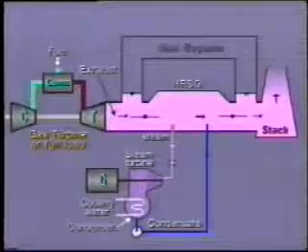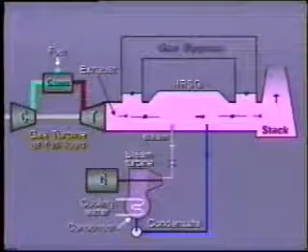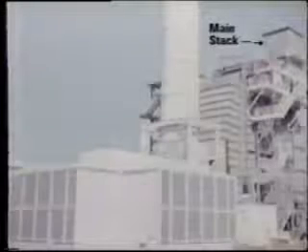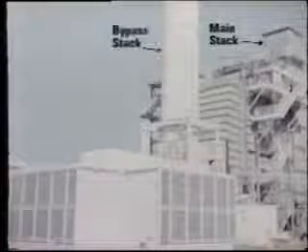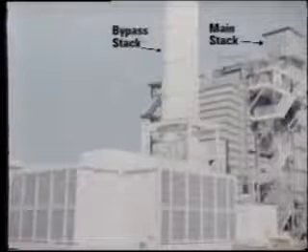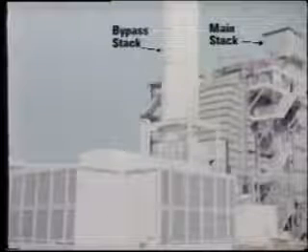A particularly difficult area to seal is that of the dampers. Various damper arrangements are employed. We may have, for example, a separate inlet damper to the HRSG, a separate exit damper from the HRSG to the stack, inlet and outlet dampers on the bypass, or a bypass damper to a separate bypass stack. This eliminates the need for an exit damper from the HRSG.